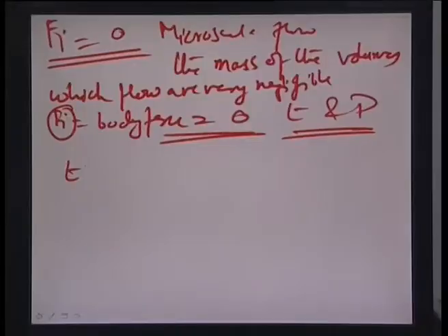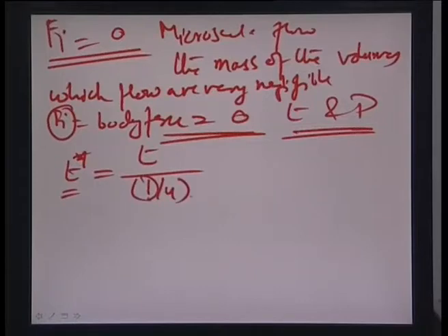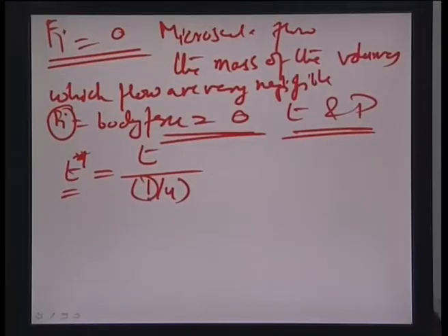So, let us figure out what this scale would be. T star would definitely be equal to the time in this particular scale, T, divided by a time equivalent in the scale that we are considering, and we already have the corresponding scaling parameters for the micro scale, d and u, for the length and the velocity respectively. So, d by u definitely would give an idea of what kind of time scale would be appropriate for the micro scale at which this equation is being scaled down. And so, we can represent T star as T by d by u.